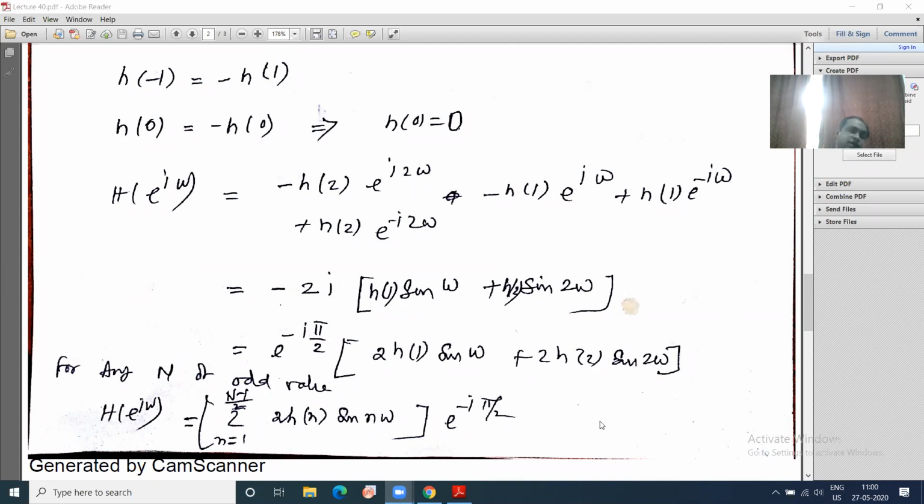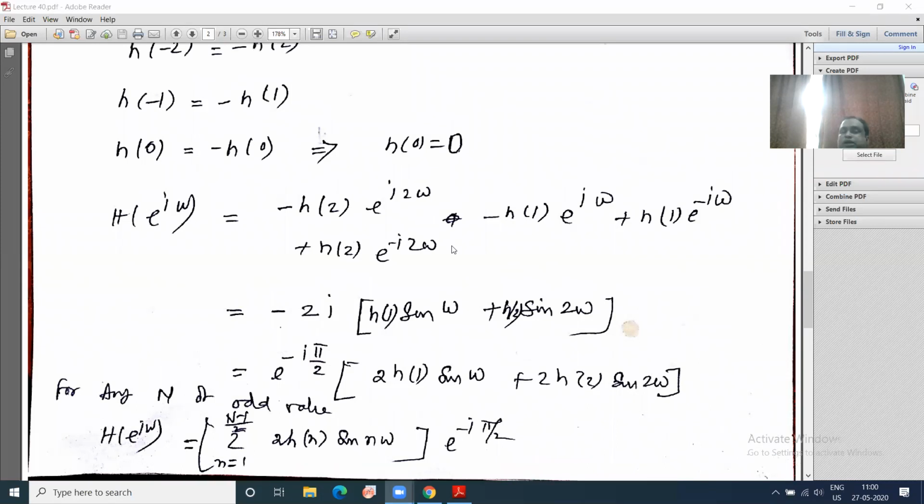However, in filter design also, this is easier to handle compared to n-1 symmetry, because they have either constant phase or no phase information. So linear phase, which is an important criterion of FIR filter design, is not a big issue with respect to this kind of symmetry. Is it all right? Or if you have any doubt?